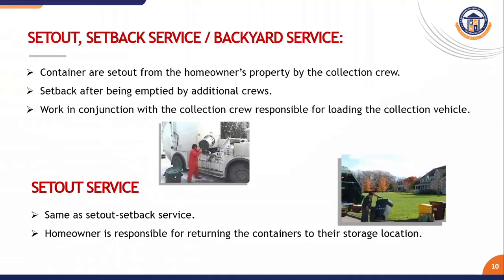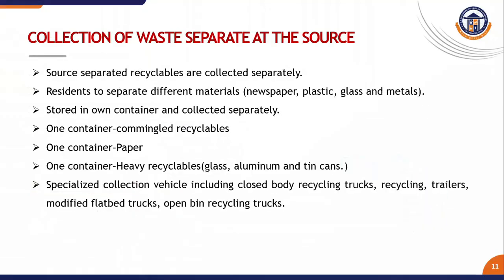Set out, setback service, backyard service. Containers are set out from the homeowner's property by the collection crew, and set back after being emptied by additional crews, working in conjunction with the collection crew responsible for loading the collection vehicle. Set out service is the same as set out setback service, but the homeowner is responsible for returning the containers to their storage location. The next one is collection of waste separated at the source.